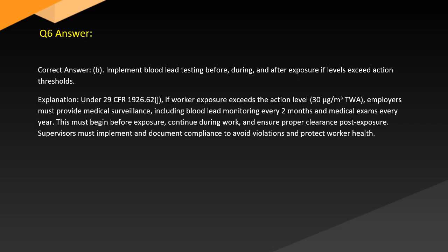Answer. Correct answer B. Implement blood lead testing before, during, and after exposure if levels exceed action thresholds. Explanation. Under 29 CFR 1926.62(j), if worker exposure exceeds the action level, employers must provide medical surveillance, including blood lead monitoring every 2 months and medical exams every year.